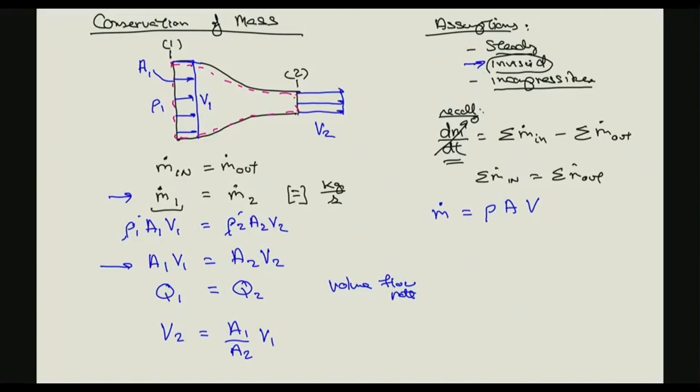Okay? So for incompressible flow, we expect that a converging passageway would accelerate the flow. If the flow is going like this, we would have a diverging flow channel, and that would decelerate the flow. Okay? All right, very important to know.